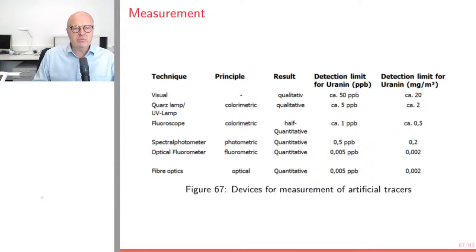You should mention how you measure in a permit application. The best solution is always to use a spectral fluorometer, which costs about 30 to 50,000. If you cannot afford this, you should at least have a filter fluorometer that is suitable, and understand the chemistry of your measurement, namely the pH dependency.